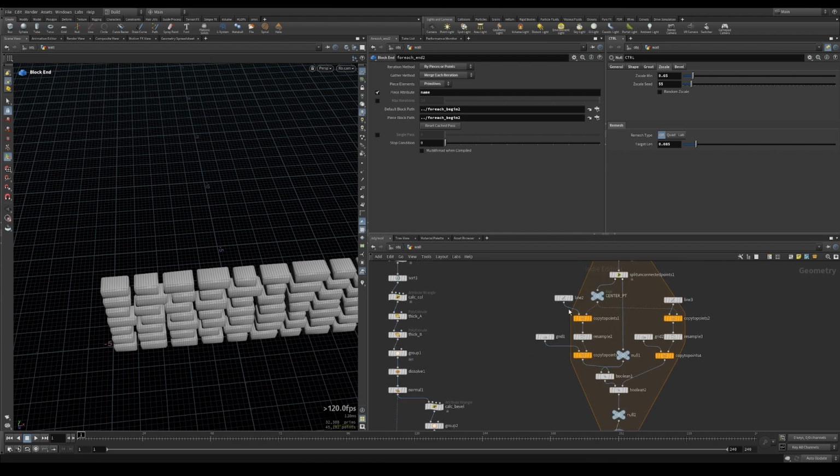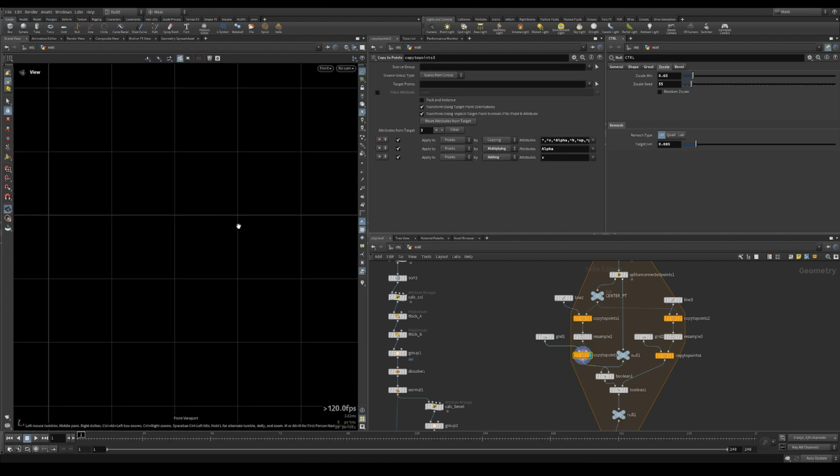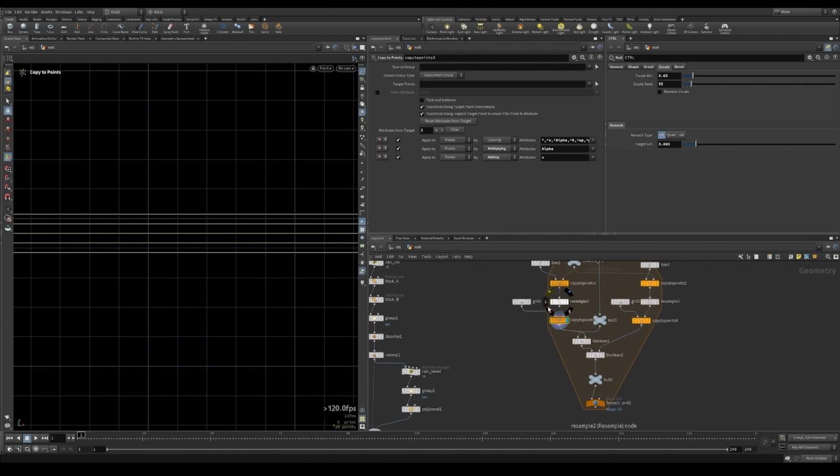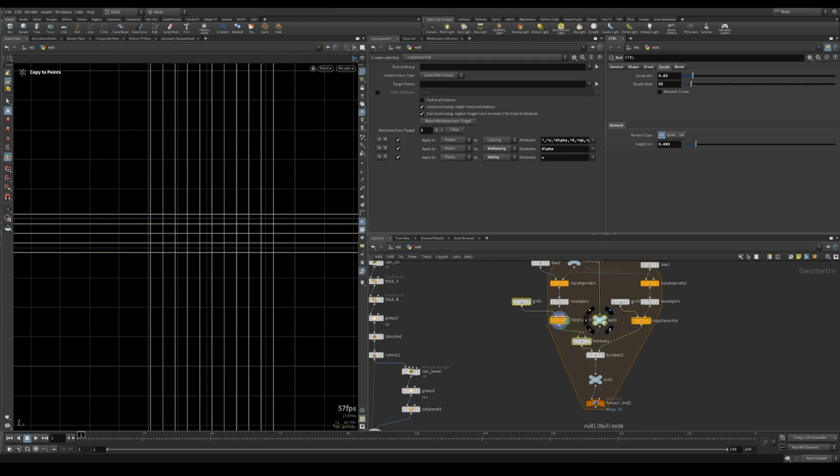The first is that if we have, let's say, no grout and no bevel, the curve will be basically matching the sides of our brick. This will generate a cutting plane on the end and on the start of the geometry and may cause issues with the boolean. So what we want to do is, after the resample, let's make a little bit of room.